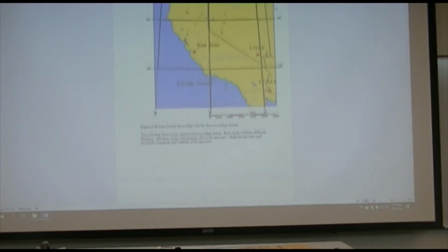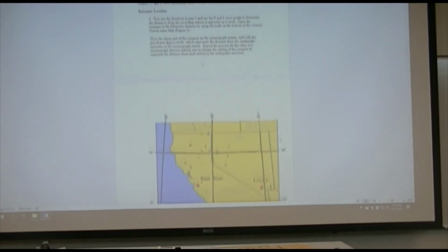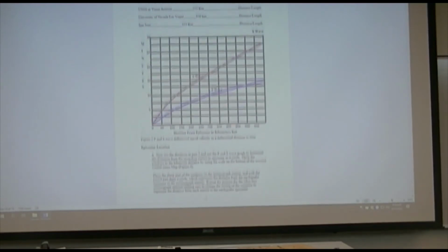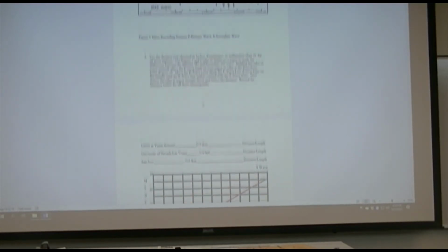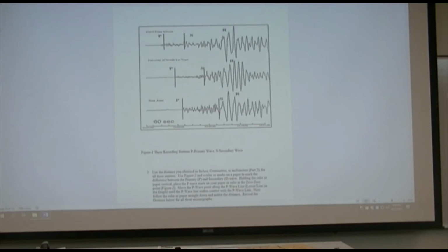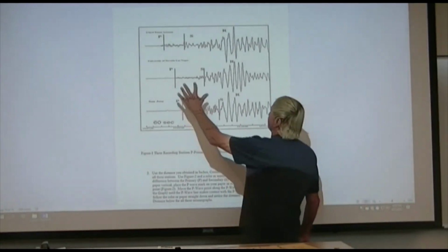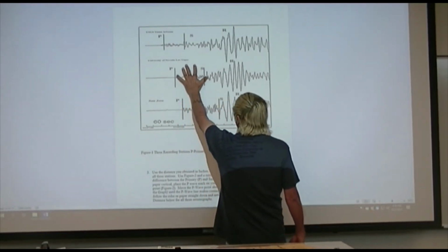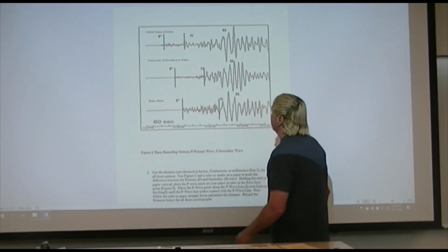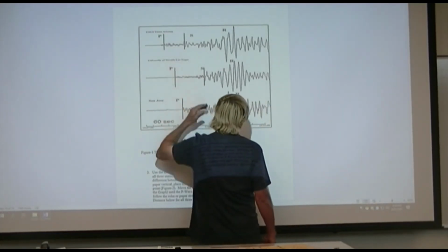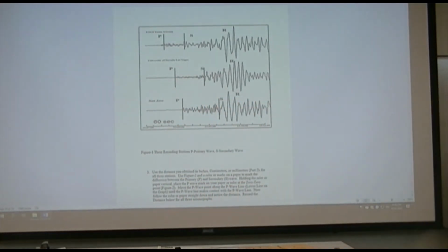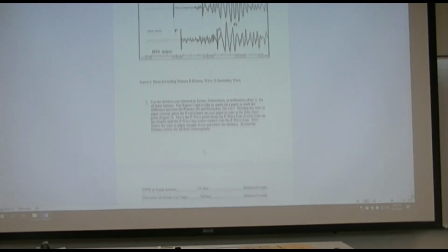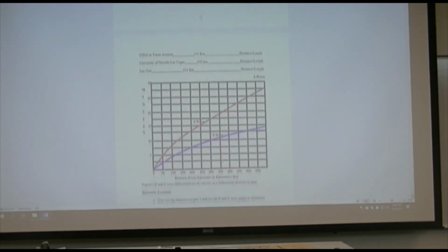I can't go too fast, otherwise it'll go to pages far, far, far away in another galaxy. And this is where we get this 40 seconds right here. The difference of arrival between the primary and the secondary waves. We're not too concerned about Las Vegas or San Jose. We're really concerned with Yuma because it's closest, and this is the seismograph we focus on for the determination of the time. So we subtract that 40 seconds.